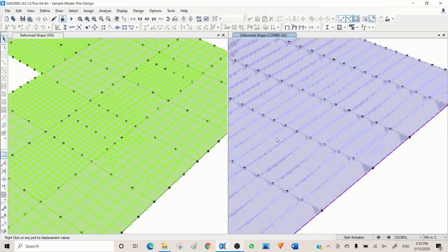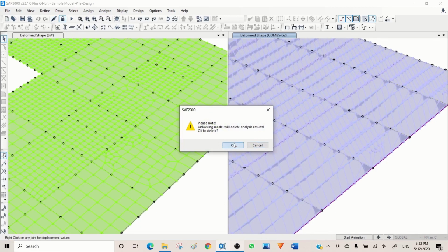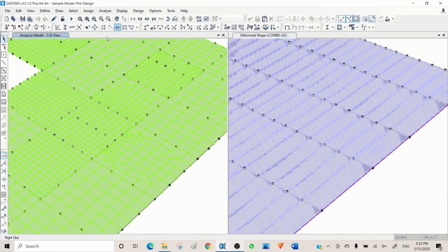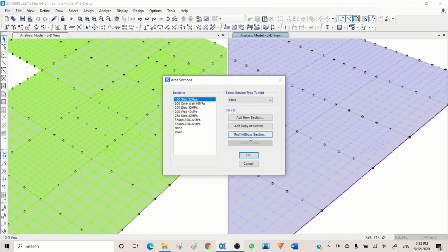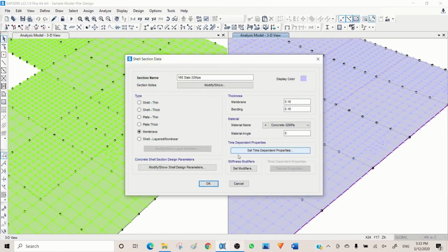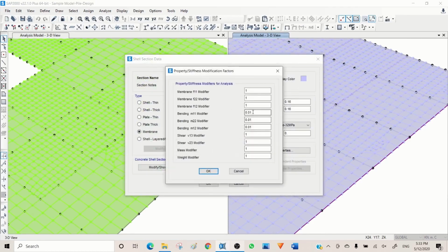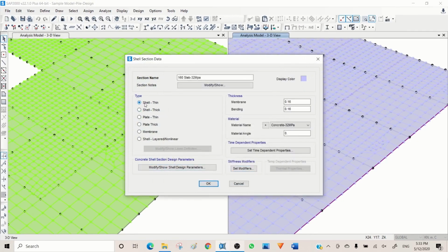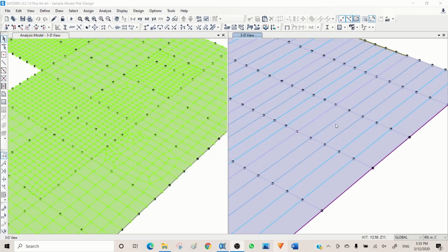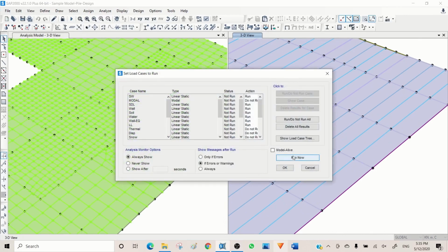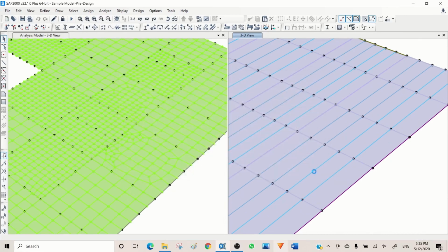Okay, that's a really good example, and let's go back and again change the stiffness to a reasonable amount. So I change it to 0.01, just 1%, which is here. Okay, so I just need to go back to shell thin and press OK and OK. So I use 0.01. Let's see what's coming up, because last time you remember the moment here was 70.